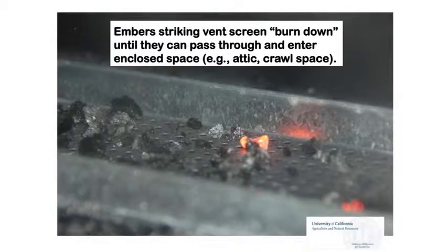From a fire perspective, vents have been shown not to be so good because they allow embers in, or firebrands in, and then they ignite fine fuels in the attic. And even so, how many of you store stuff in your attic? So I take it they would be combustible things like newspapers, magazines, or memorabilia, whatever, things like that. So even if you don't do that, a lot of debris can accumulate over time, just like in that under roof area that we saw.